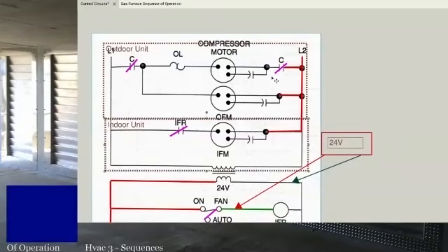Side note, bonus one, because there's one more I want you guys to catch, hopefully. On a compressor, the connections at the terminals could be bad. It could look like everything's tied in good in the control panel, but if you actually go to the wires on the terminals of the compressor itself, something could be wrong with those wires.